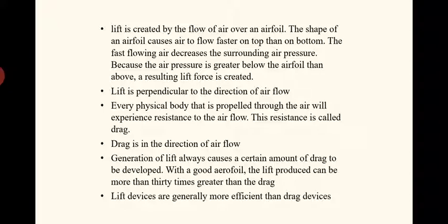Coming to the drag, every physical body that is propelled through the air will experience resistance to the airflow. See, air is blowing in a particular direction. So if it is hitting a particular body, always a resistive force will be exerted by the body on the air, as well as the air exerting a force on the body also. Because of that force, the body can be moved. That is what is happening in the case of a wind turbine working on the drag force. This resistance is called drag. So drag is in the direction of the airflow. Here lift is always perpendicular to the direction of the airflow.